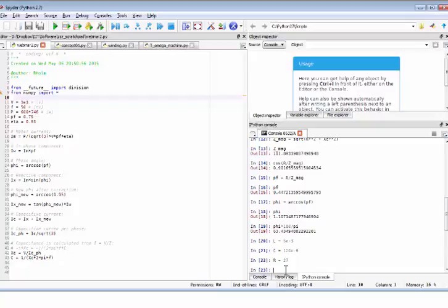Now, the complex impedance would simply be R as it is, plus j times the inductive reactance, which would be 2 pi f multiplied by L, if f has been defined, otherwise we will just do it afterwards. The capacitive reactance is minus j multiplied by 1 over 2 pi f c.